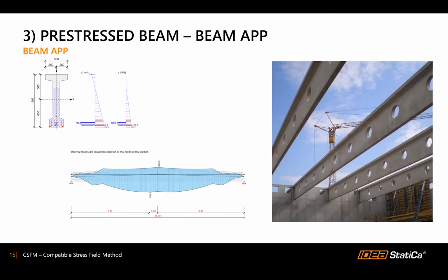There is also some changing of the stresses in the tendons, and the evolving of the strength of the concrete. This effect has to be captured by the design of pre-stressed structures generally, not only for prefabricated structures. This is valid also for bridges, and for all the structures. So this will be the first example, where I would like to show you how to design and check the pre-stressed beam using construction stages analysis.